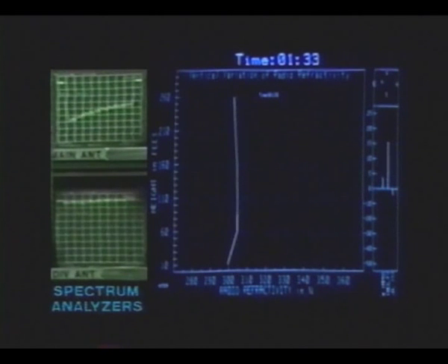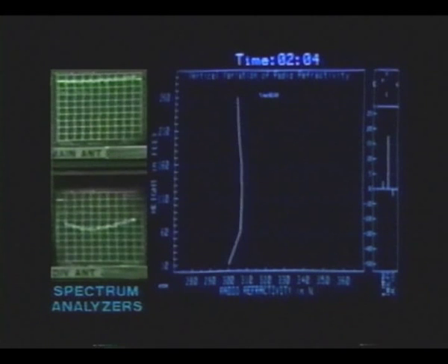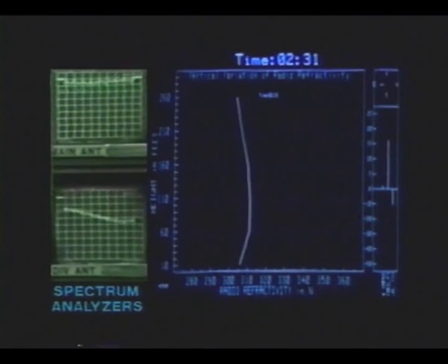Then, an out-of-band notch produces a 15 dB slope across the 30 MHz radio bandwidth. Here, the meteorological display is again slowed to aid our view, but the spectrum analyzers remain in real time. Between 2 and 2:30, the diversity receiver experiences a 20 dB notch on top of a 25 dB flat fade. Between 2:30 and 3 a.m., the diversity receiver has a 30 dB notch in band, which rolls out of band to produce a 10 dB slope across the 30 MHz bandwidth.